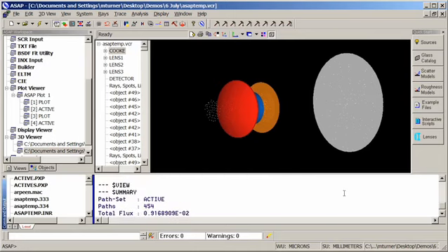By using the summary command, we can also get information about the energy, the total flux on the detector. And when I know that I initialized my energy to have units of 1 watt, this tells me that there is a very small amount of that energy actually making it to the detector as these Fresnel reflections, and that they're highly dispersed across that detector surface.